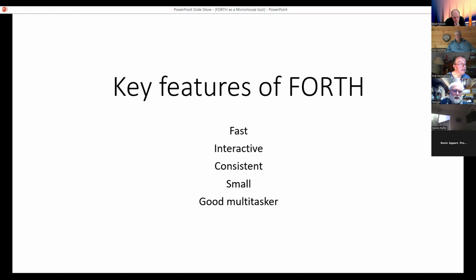Then it goes into a wait loop until the next timer interrupt. During this time, the other tasks can get a go. The other tasks can be the solving algorithm, any data logging, and the user interface. As long as these all pause before the next timer interrupt, everything is fine. Cooperative scheduling removes all the issues of resource clashing because you can be sure no other task can run until you pause.